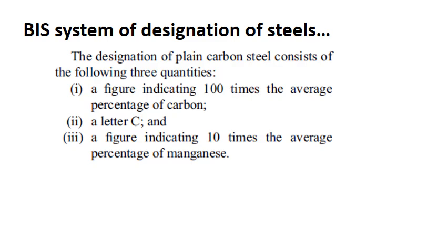They might target some percent, but they can achieve only less, because some would go through the slag, some would escape in the air, so there will be losses in different forms. That is why they add more than what is required while casting, and then when they check the chemical composition, it will vary from point to point, and then they take the average one.